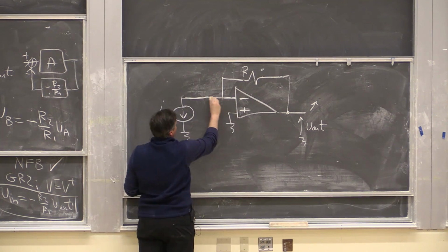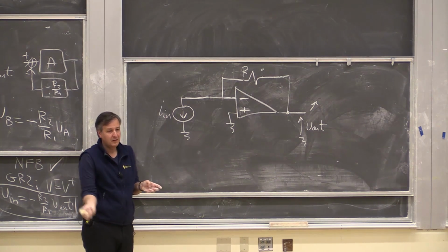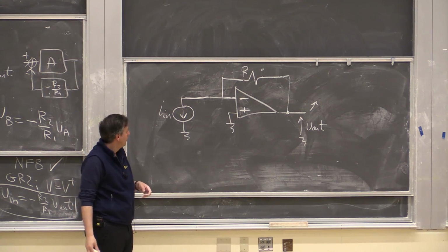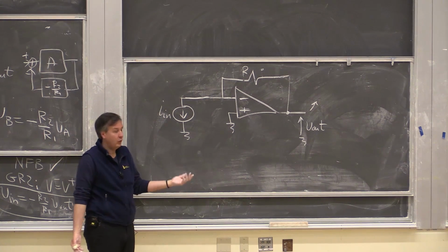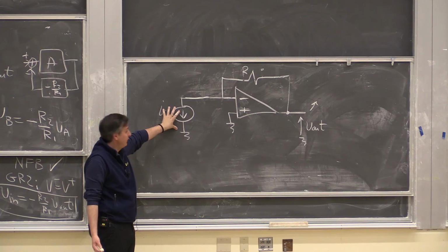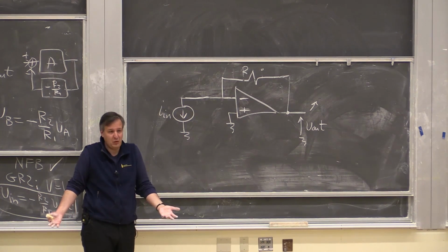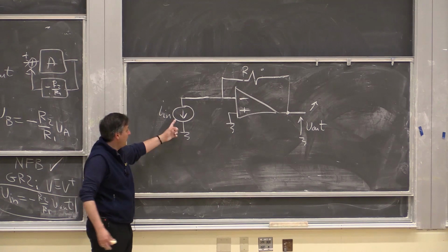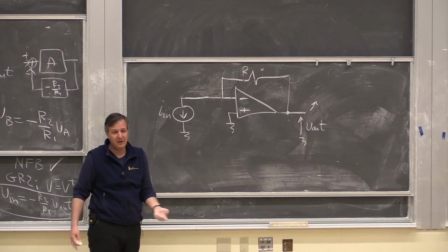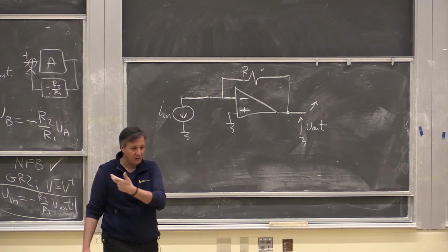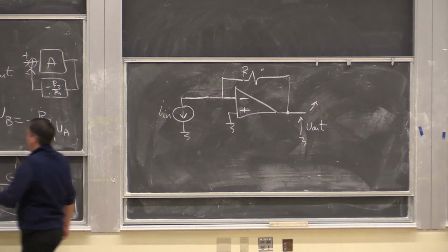Okay. Now think about it. Yes? It doesn't matter what direction the current is flowing, the source current, because you just null it. In fact, this source current is changing. It could be positive and negative from the same source. It's changing in time. Now, you were right in a sense that this does remind you of the inverting amplifier.